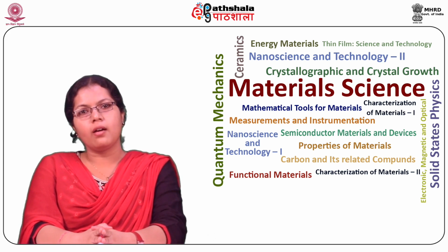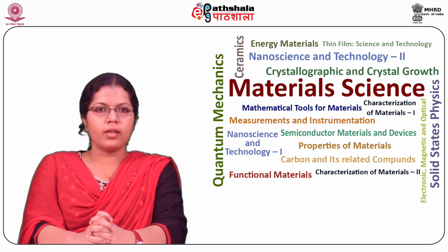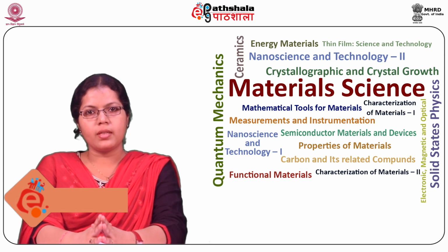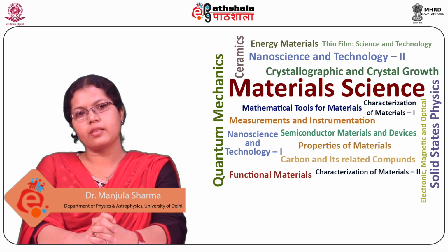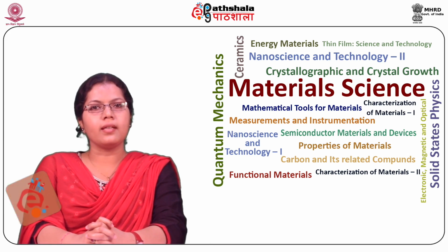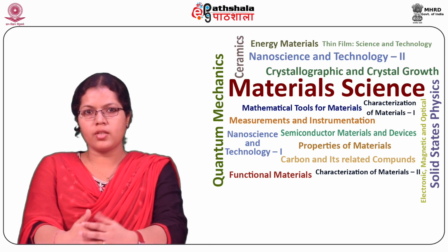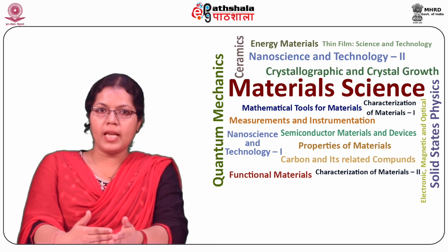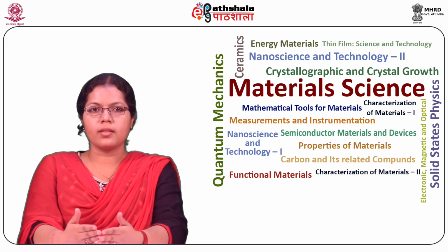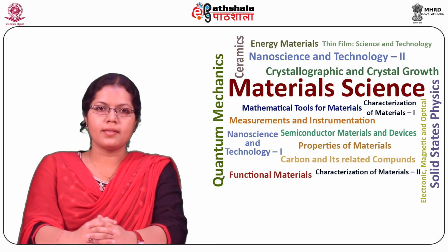Also, the criteria of selection of transducers were discussed, which were mainly the fundamental parameters, environmental parameters, and physical conditions. We understood the parameters necessary for the compatibility of transducers with the next stage, like impedance matching, excitation voltage matching, and sensitivity tolerance matching. At the end of the module, we discussed the smart sensors.